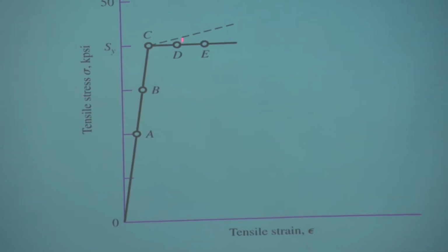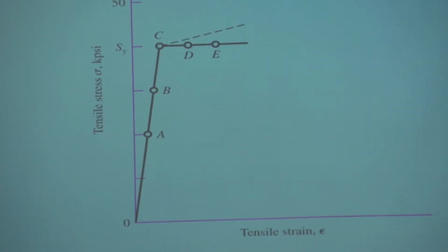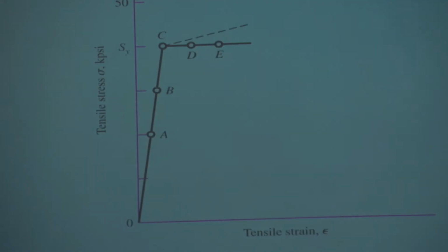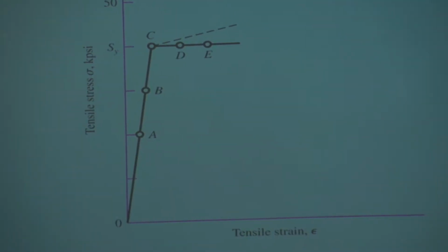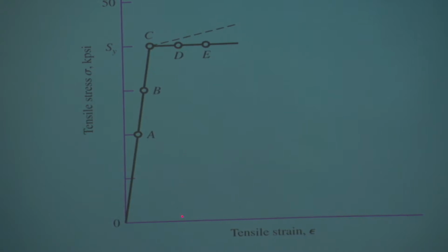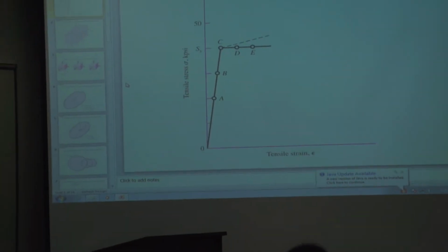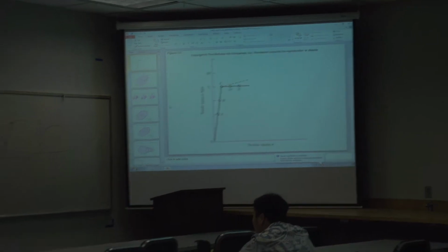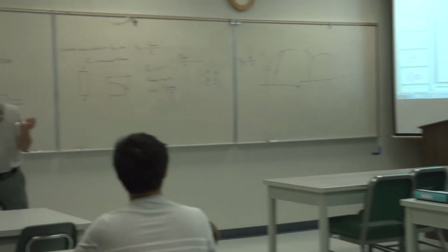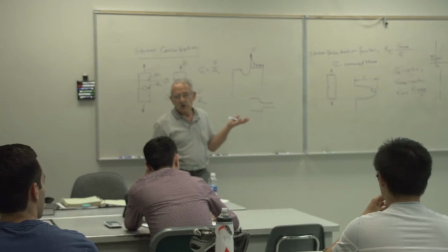So, for example, if the strain that I measure via these strain gauges in this position is over here, and then I take twice that, I go over there, both those stresses are equal to Sy. In reality, the stress concentration factor there is 1. In other words, it's decreased from 2 to 1.33 to 1.2 to 1.1, and therefore 1. So in this case, we don't use the stress concentration factor.